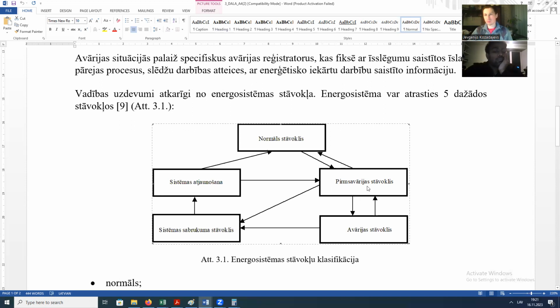And in this case, we see the arrows. So we could come to this pre-fault mode and could go back to normal, because the relay protection could deal with the fault on the line. Yes, disconnect the line and everything goes okay. We can come back to normal operation. Okay, in this case, yes, if we come to a fault regime, we could come back, because this under frequency automation disconnected the consumers. We are again in a balance, and we come back to this pre-fault regime, yes?